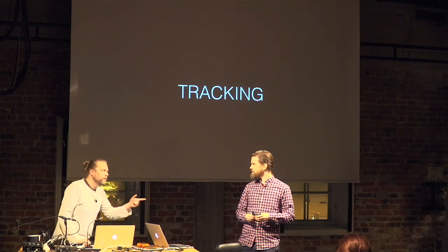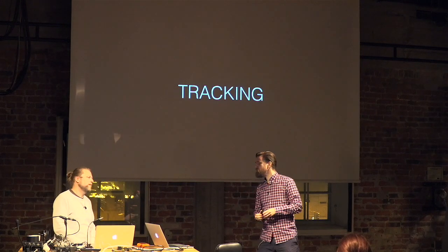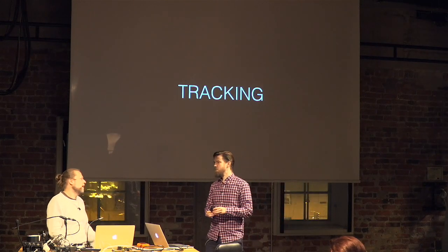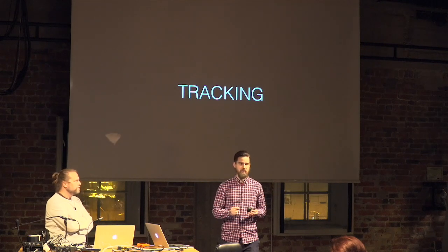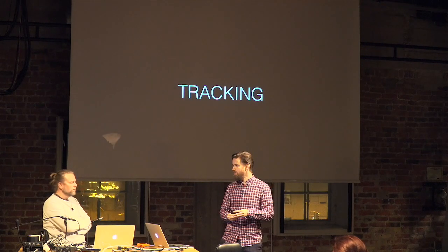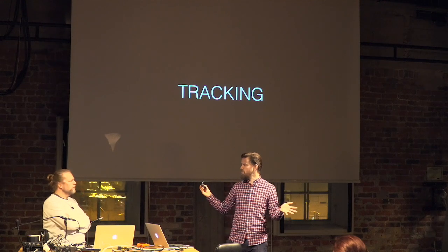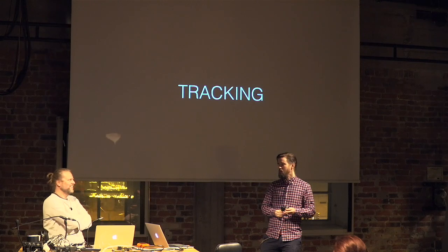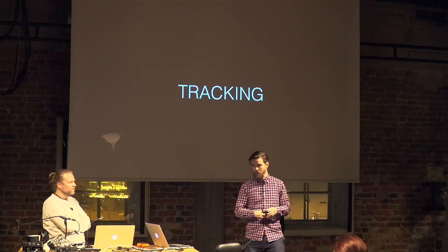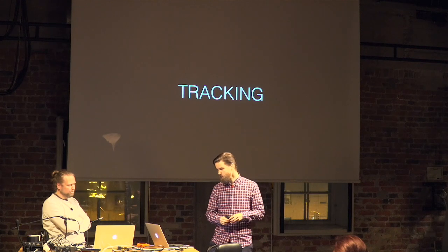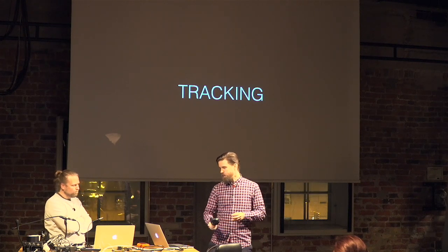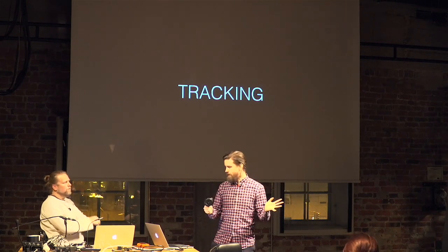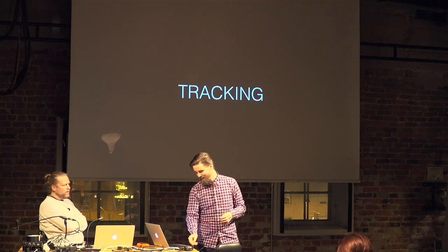Yeah. But the thing with a real camera-based motion analysis system is the space. With that you can track a bigger space than this, like 10 or 12 meters, and it's millimeter accurate. And this you can use up to a square of about 4 or 5 meters, but it's still quite a big space that you can use. So this and the high-end system are sort of compatible in our thoughts at the moment.